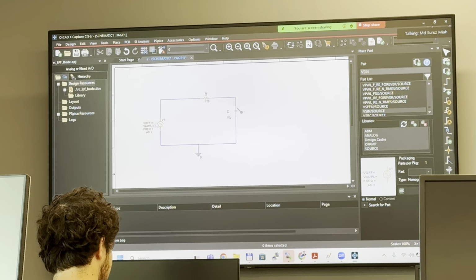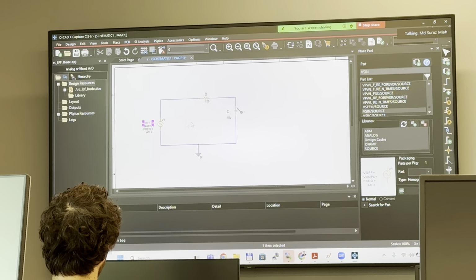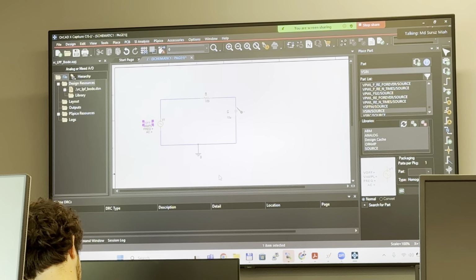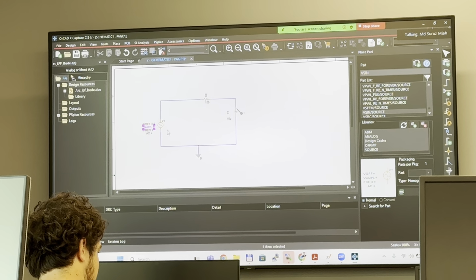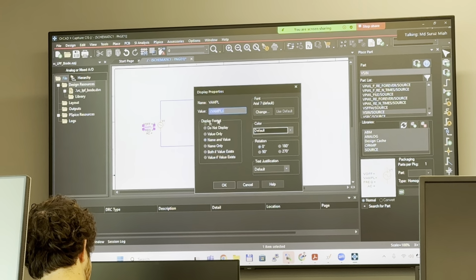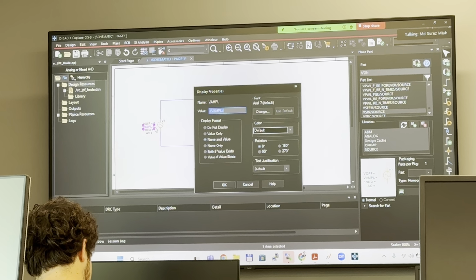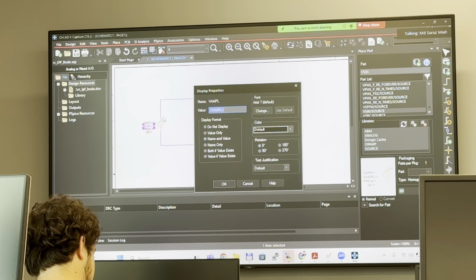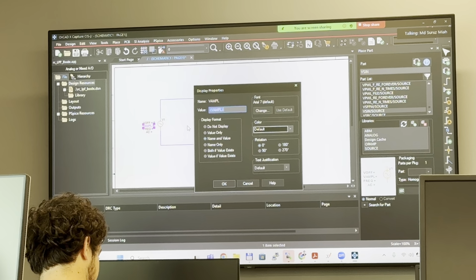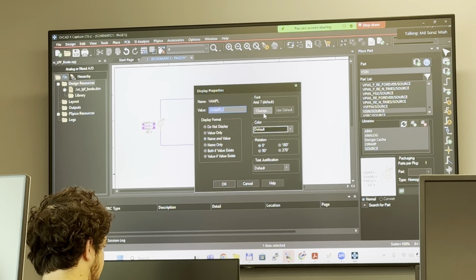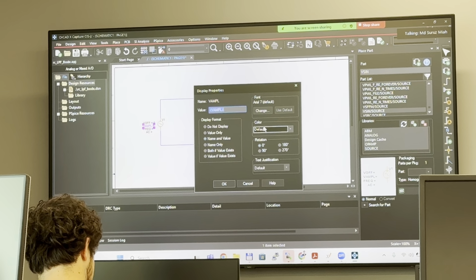Okay, here you just have to give parameters, otherwise it's going to give you an error. Offset 0. Amplitude: there are 3 components, but you can take any of the components, because these would not be taken into consideration, since we would be running the simulation which is going to be magnitude versus frequency.